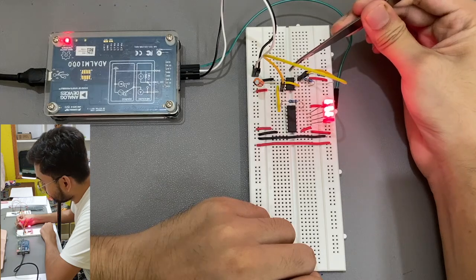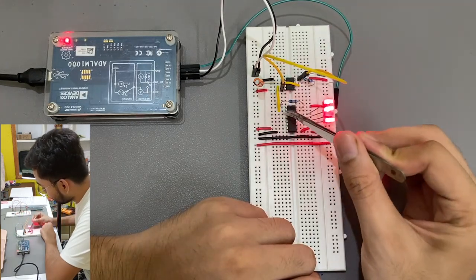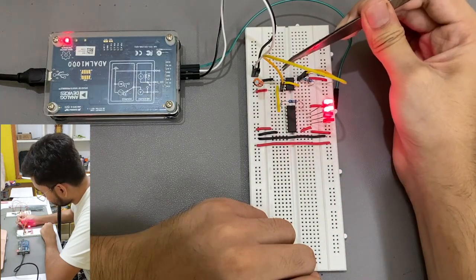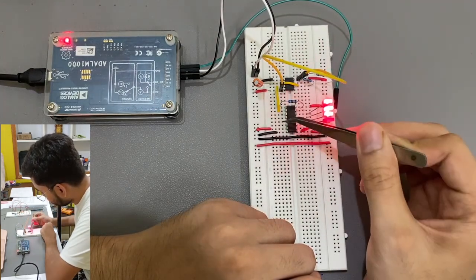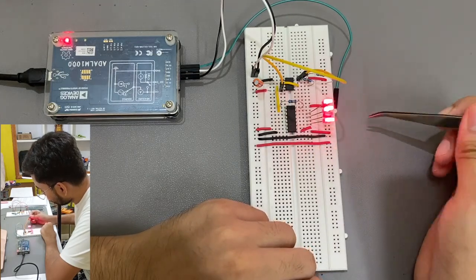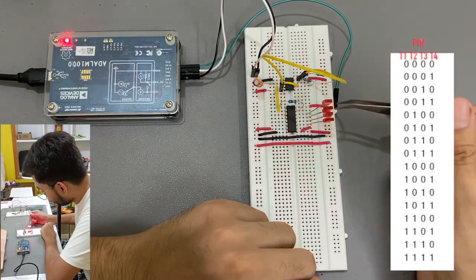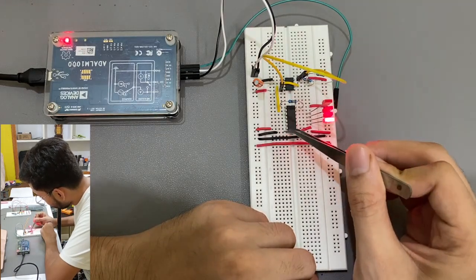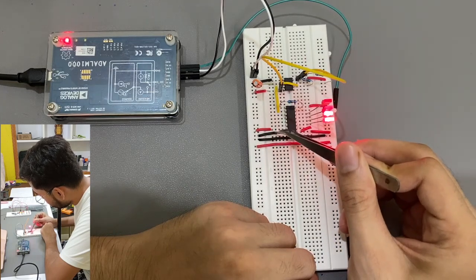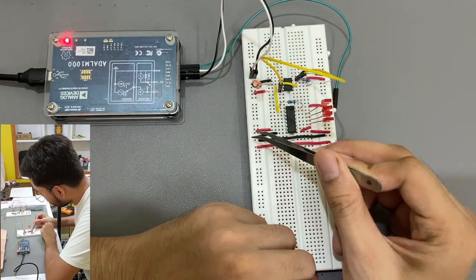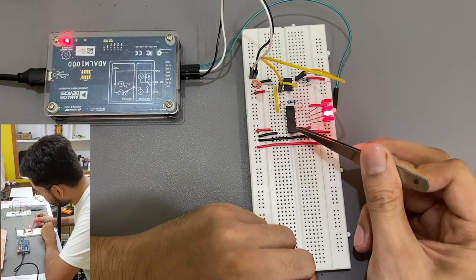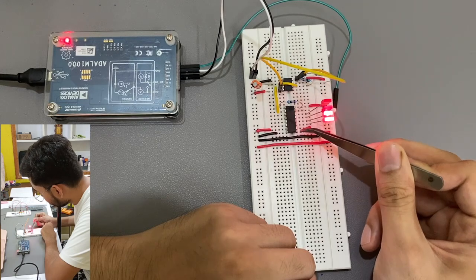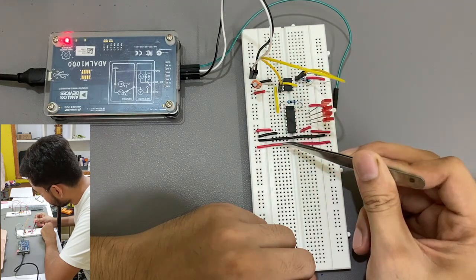The third pin of the 555 timer IC, which is the output, is connected to the second pin of 74LS163, which is the clock pin. The 555 timer IC is giving output to the clock pin of 74LS163, and 74LS163 starts counting 4 bits from 0000 to 1111. This LED shows us the count of 4 bits, and the 8th pin of 74LS163 is connected to ground, and the 7th pin, which is ENP, is connected to input voltage, or we can say it is set to high. The 9th pin, which is the load pin of 74LS163, is connected to input voltage and also connected to ENT. This black and red wire shows ground and input voltage.